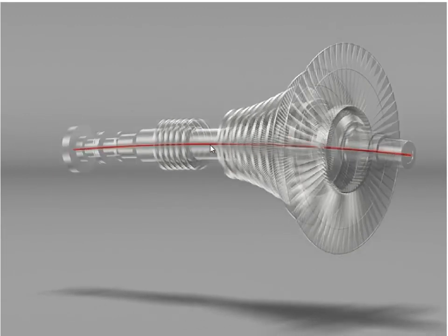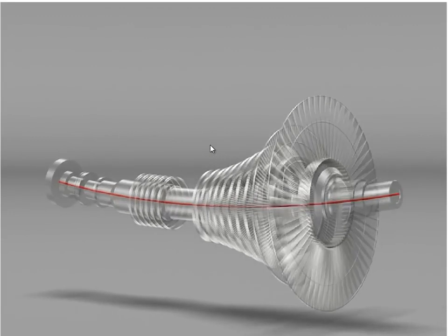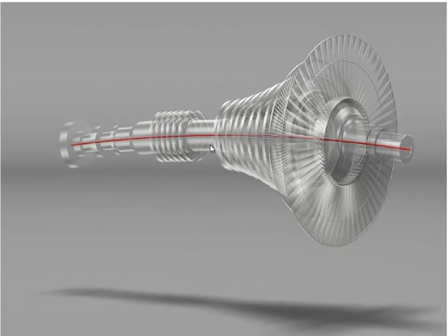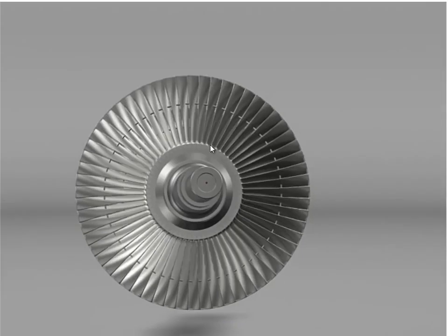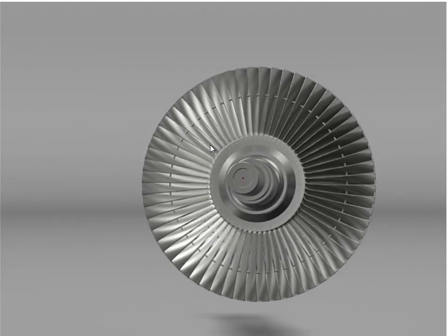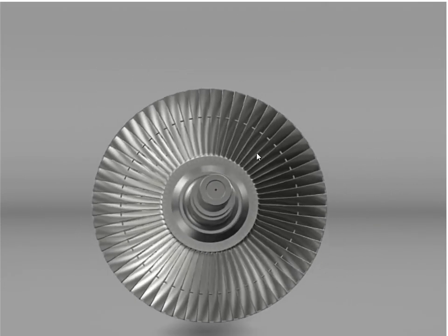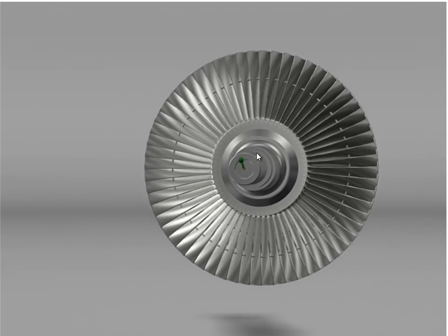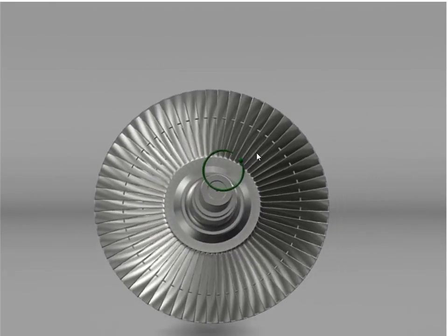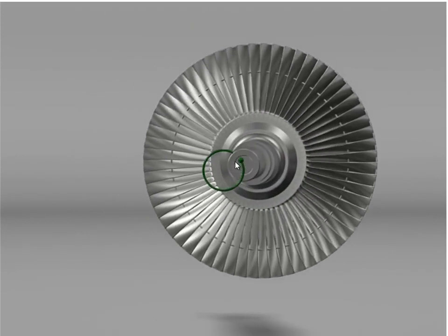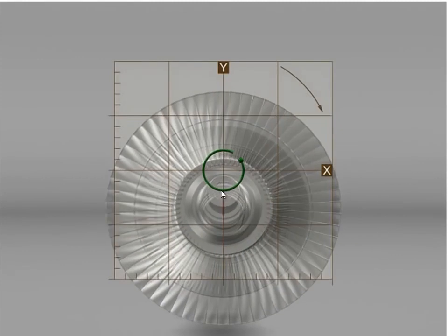So in this instance, exaggerated, that's the motion at the first critical, let's say. A lot of detail we could go into, but I'd be interested in how I take measurements to tell that's what's going on. Well, imagine if we had our two proximity probes at 90 degrees apart, taking the measurements, and we compared the two sine waves. We end up with a Lissajous figure, as it's often called, or an orbit. We plot the two sine waves against each other. We end up with a circle, if it is moving in a circular motion.